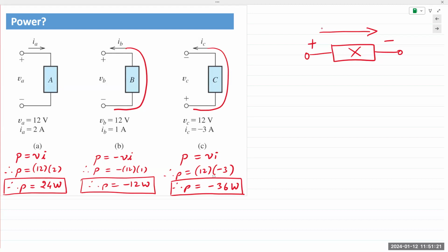If it's a source, it is supplying energy. So the current flow for a source goes from minus to plus. Again, that will come in later examples, but since the question was being asked, I'll point it out right now. Current for all passive elements, basically resistors, capacitors, and inductors, always goes from plus to minus. Current for a source will always go from minus to plus.